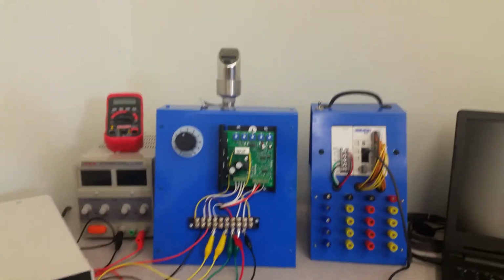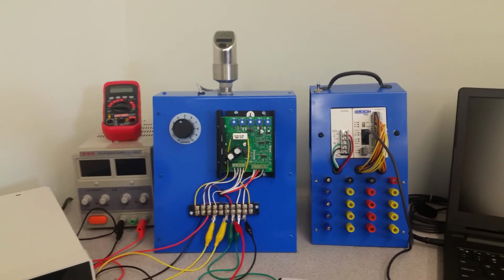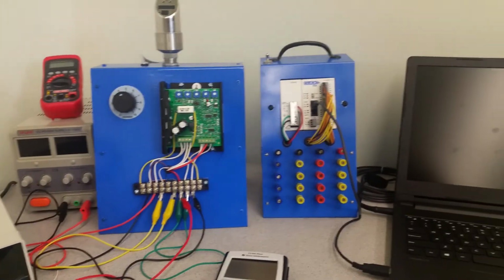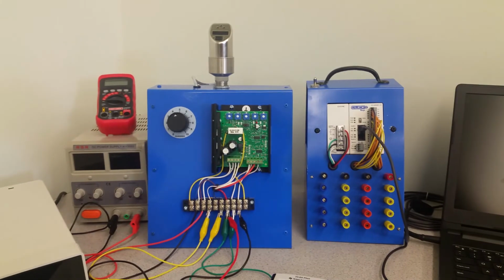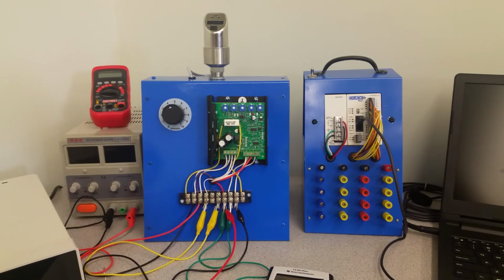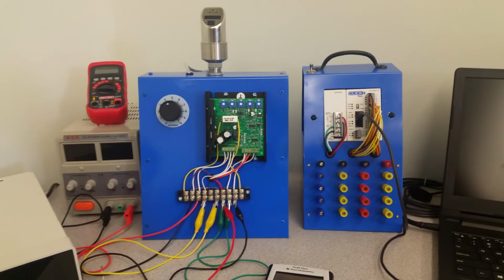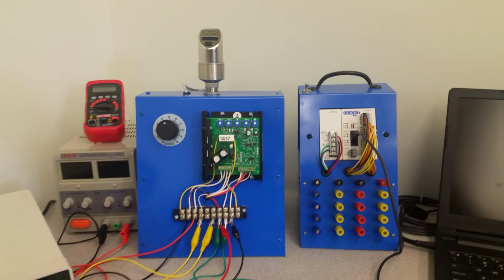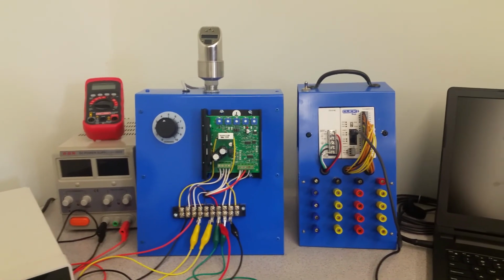A lab trainer that I recently constructed uses a temperature probe and a heater made out of light bulbs driven by a DC drive. This is then driven by a CLICK PLC with analog output and input modules. And the student is required to control the temperature of the probe. I found that not many people get good experience with analog systems, even though they're still used widely in industry. I've constructed 2 of these trainers so far, and this is something that the students actually do in the ELC 228 class.